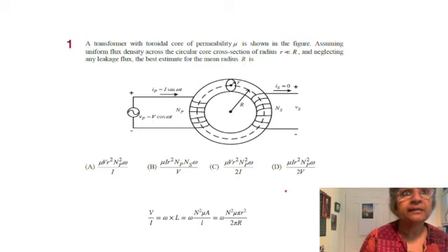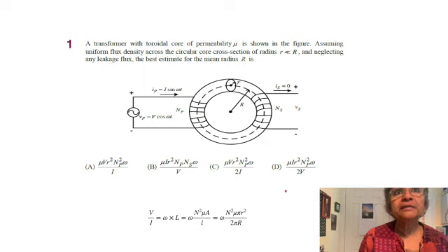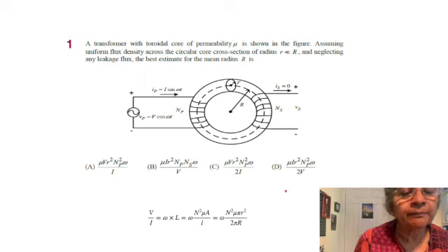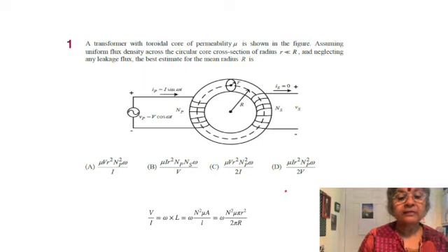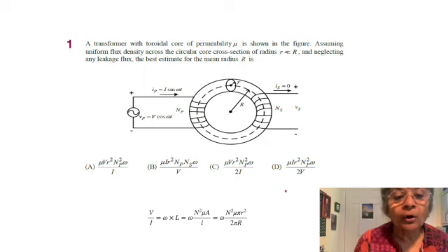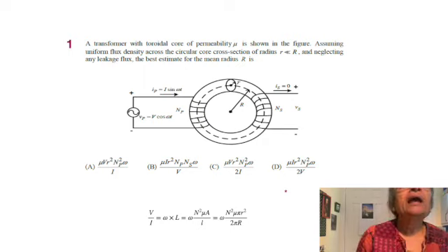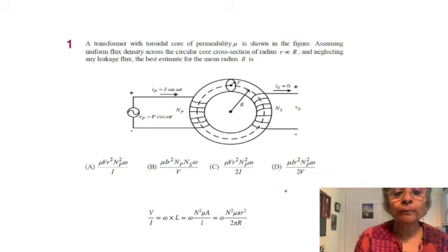And what is self-inductance? It is given by NP square, because NP is the coil winding specific to self-inductance of this coil or the system or this toroid. So we have NP square, then mu naught mu r A, which is the cross-sectional area of the iron of the core, that is equal to pi small r square as can be seen there, and then divided by L, which is equal to 2 pi capital R, that is the total length.